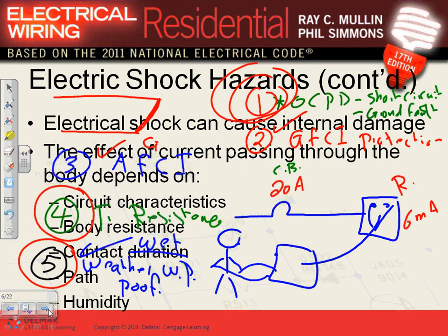Any question, guys, about these 5 types of protection for one circuit? Who cares about these protections? It's supposed to protect us as human beings, either from being electrocuted or burning our homes, right? Look at all of them. Short circuit, burn homes. Ground fault, burn homes if it doesn't work. Arc fault, burn homes. Ground fault protection, protect us from being electrocuted. Weatherproof, protect the equipment. And by protecting the equipment, protect us, right? Weatherproof and tamper resistance protect from kids or anybody tampering with the receptacle.